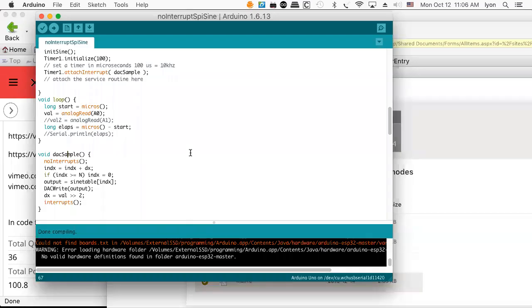So it's really good to know things like, I'm going to run at a sample rate of exactly 10 kilohertz. That has implications in terms of your frequency response, right? Because you have to think in terms of the sample rate of the DAC being twice the highest fundamental frequency you can possibly detect. The reason why is the Nyquist theorem, which says you have to sample at twice the rate of the highest fundamental frequency. That includes partials, that is the harmonics of the frequency that you're interested in detecting.